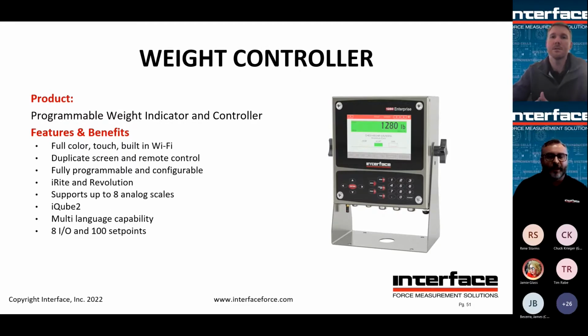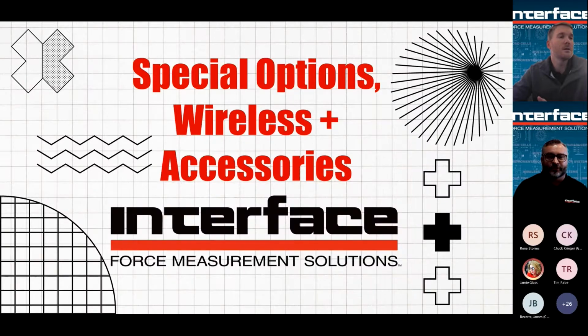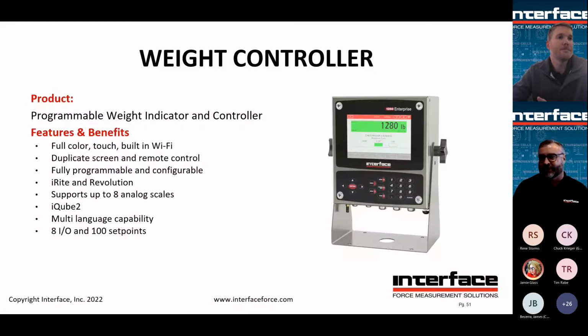Yeah, I can make a couple of comments on that too. I talked about the digital displays, which just have the basic relays. Something like this is much fancier. Maybe it'll have set points, but imagine if you shut the relay at a certain point, and then that still continues to flow a little bit. So you still get some product, for example. Something like this can actually learn and adjust the set point automatically, so you end up with the right answer. Or it can have a couple set points where it goes from a fast to a slow fill, and again kind of learns that, and takes the weight right up to the set point automatically.